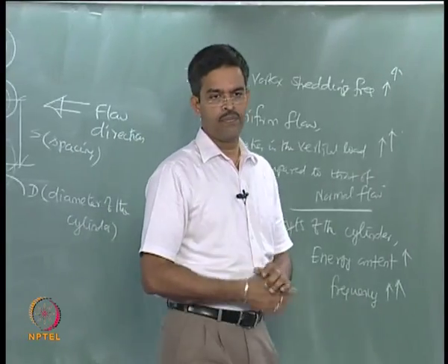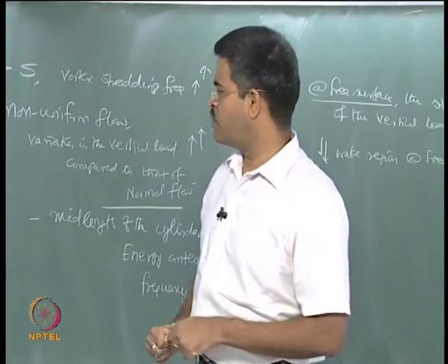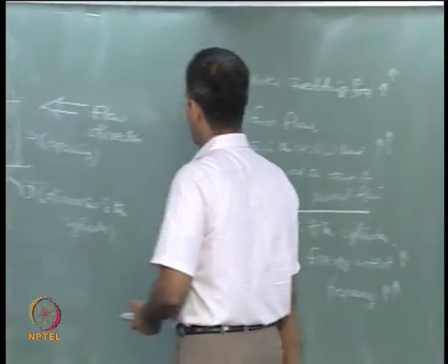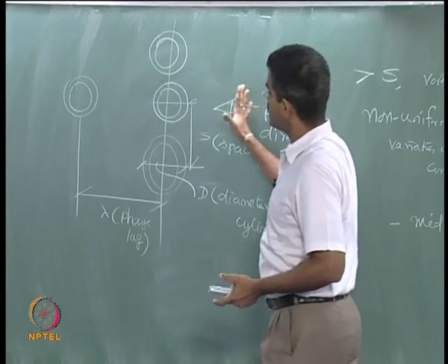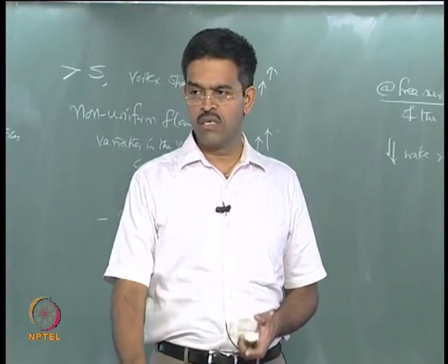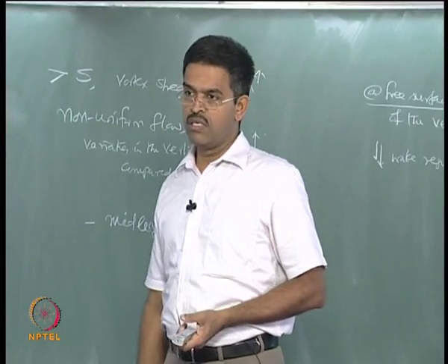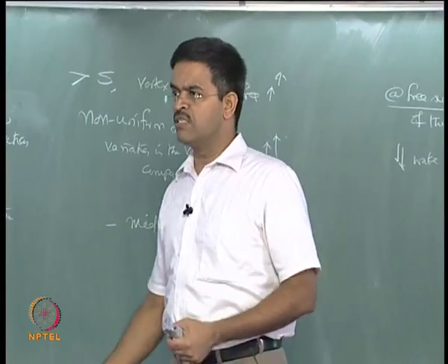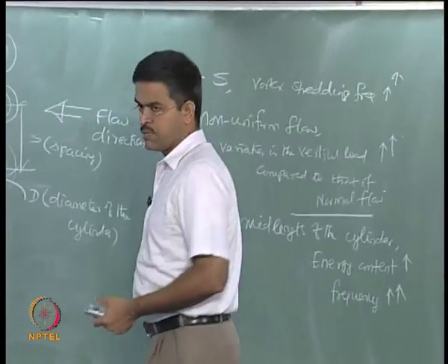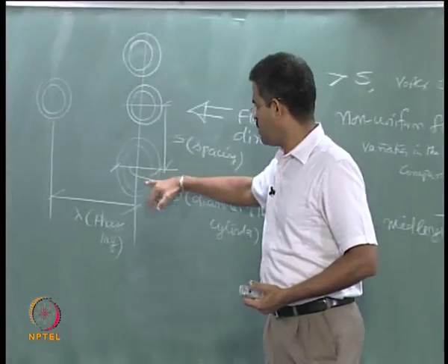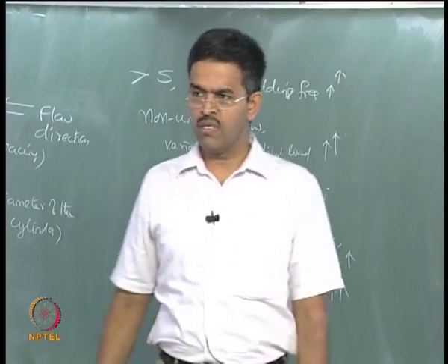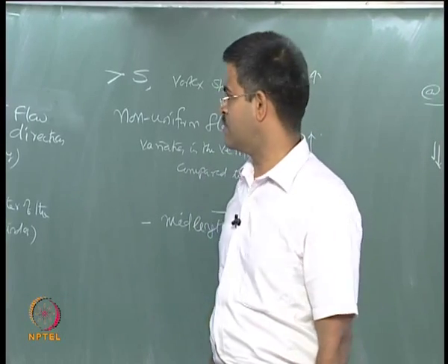So when you talk about the interference of a group of cylinders in a flow field, then it amounts to what we call blockage, because the velocity of the flow past the cylinders in a group will get reduced. And we already saw in the last lecture, in case of reduction of velocity there will be different kinds of vibration set in the cylinder itself. So when the velocity reduces, for a specific range the vibration set on the cylinders will be of a different mode. Sometimes it is in drag or inline effect, sometimes it is in transverse effect. We have seen that in the last lecture, you can look at the table later.